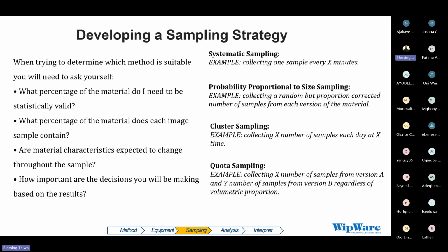In case you want to use the result of the image analysis in separation techniques, where you are more interested in a particular size class that will enhance the liberation of the high concentrate materials, then you want to get more of the fines. You want to move closer and capture more pictures from the section where you have fines, to ensure you are not losing high grade material to the fine fragments.